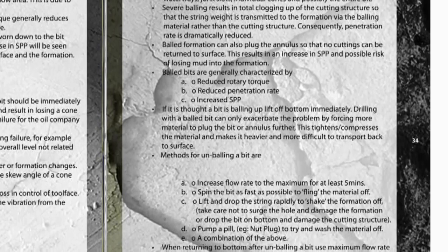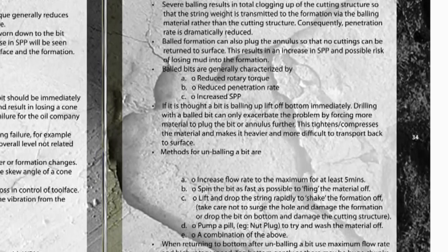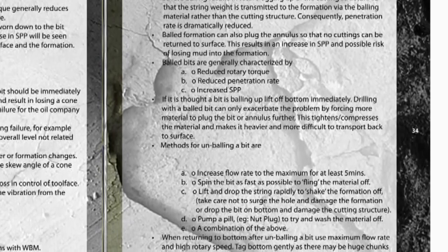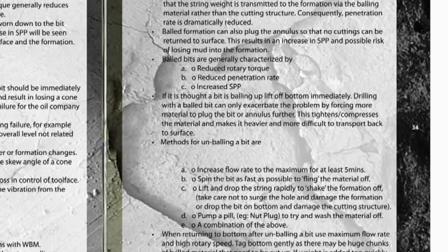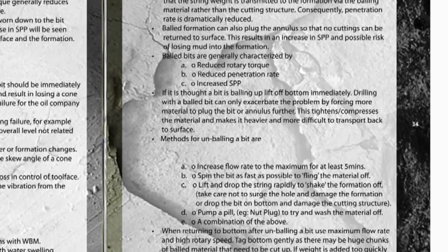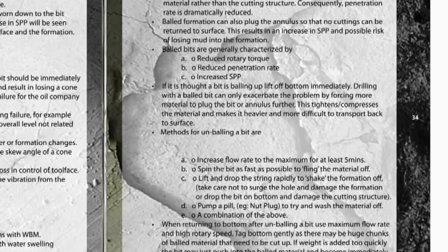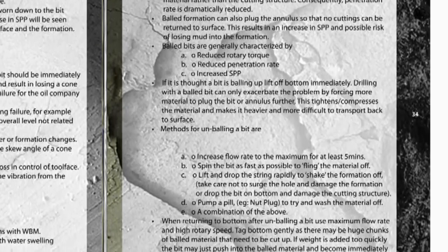If it is thought a bit is balling up, lift off bottom immediately. Drilling with a balled bit can only exacerbate the problem by forcing more material to plug the bit or annulus further. This tightens or compresses the material and makes it heavier and more difficult to transport back to surface.